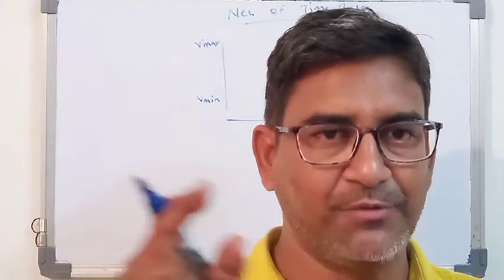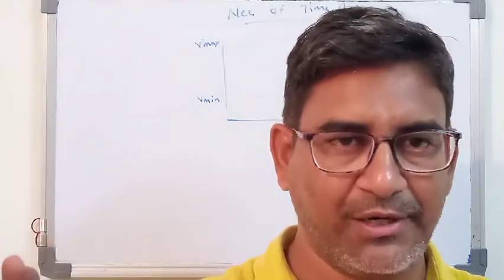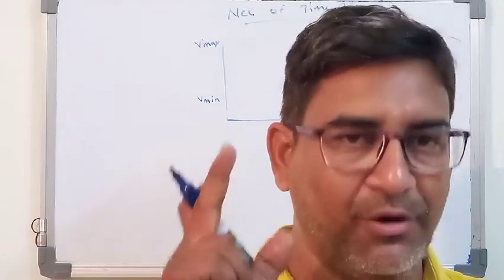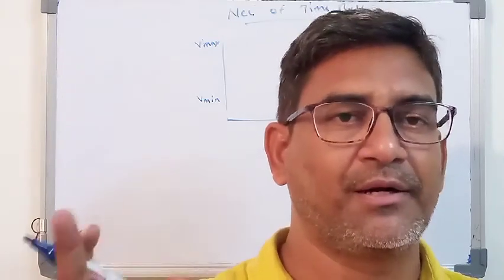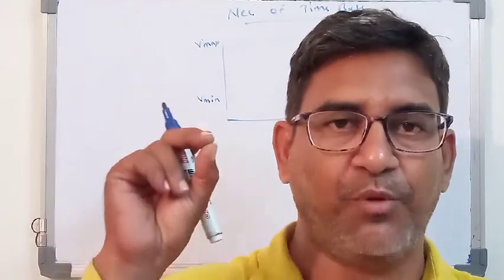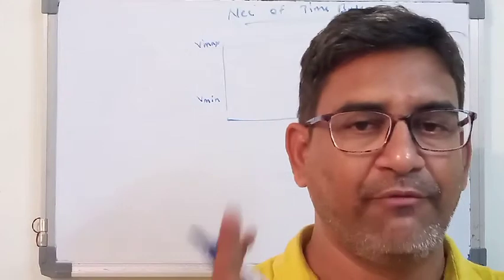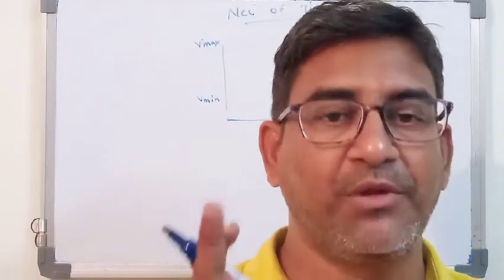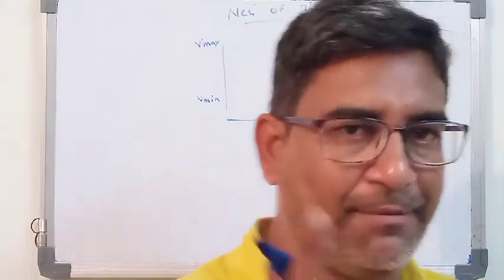When the electrons pass through these anodes, they go to the vertical and then the horizontal deflection plates. When they go through the vertical deflection plate, they maintain the horizontal direction, and as soon as the electrons pass the horizontal plate, they try to maintain the vertical direction. When the electron spots across the screen from left to right with constant velocity, the spot then suddenly returns to the starting position on the left side of the screen, and that sweep voltage is called the time base.